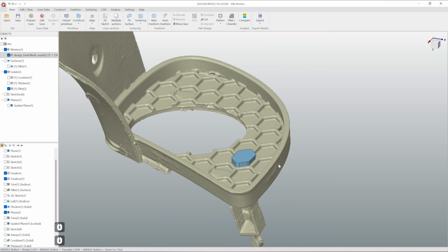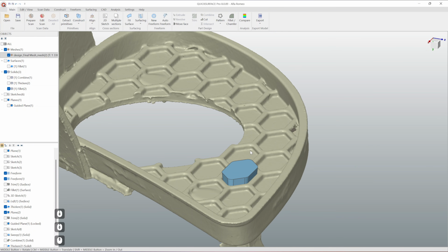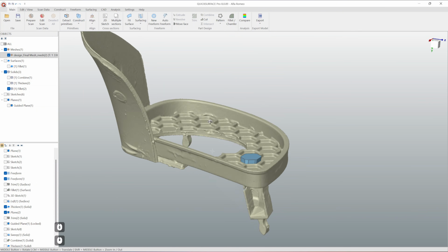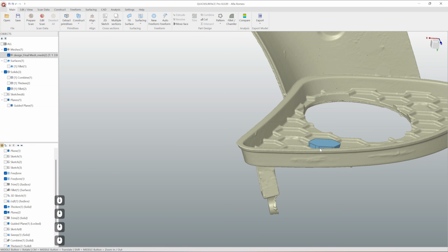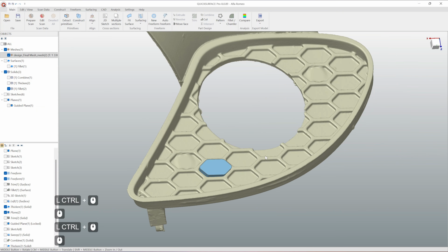Of course, we could do that in Sketch, but imagine after we would have extruded all of them, we would have to add this fillet individually on each of them. So this would be much more time, much more work, to select all these edges. Instead of that, I will try to pattern this as a solid.